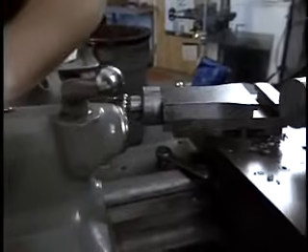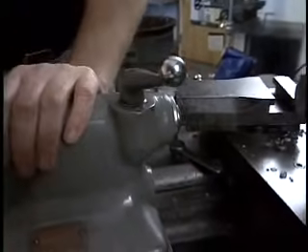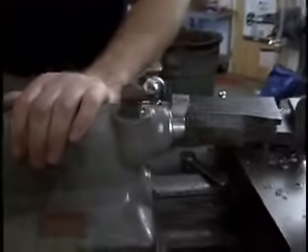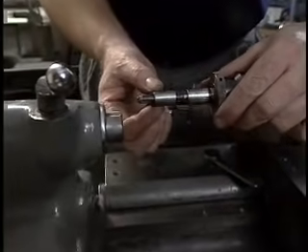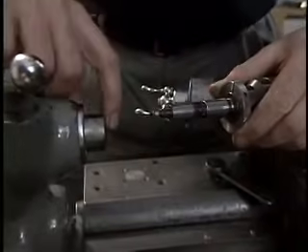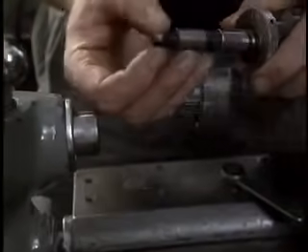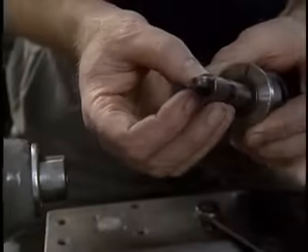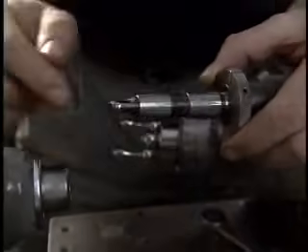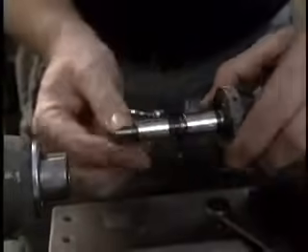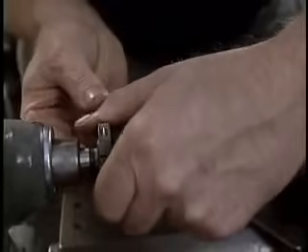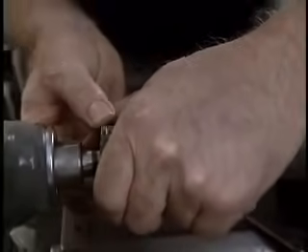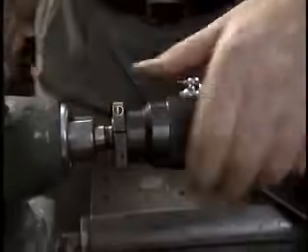Going to be putting the drill chuck into the tailstock of the lathe. You can see there's a taper here that inserts into a matching taper in the tailstock. There's a little tang with two flats on it, at the end of the taper, that locks into the inside of the tailstock, keeping this from rotating. You rotate this until the tang fits in place, push it down until it seats, and then